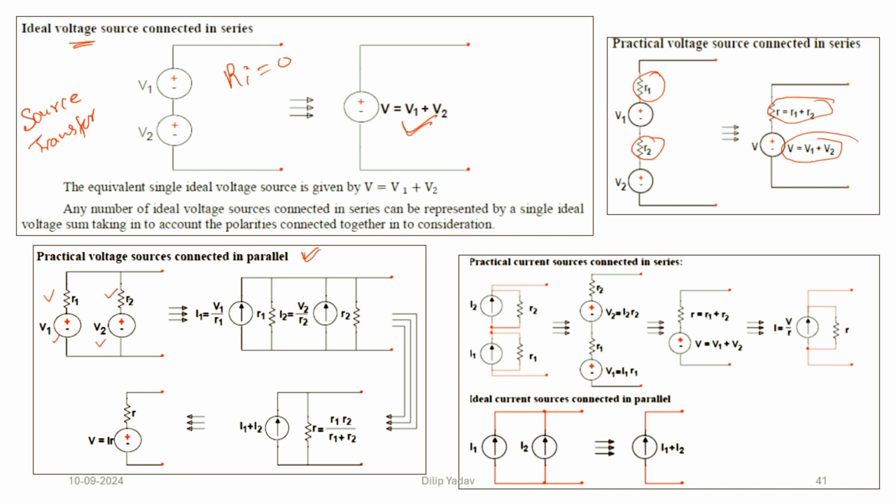So by using this, we have transformed the voltage source into the current source. The current transformation is there, and I1 is calculated like this, and I2 and R2 are calculated like this. This is I1 and this is I2. So we have transformed it. The two are connected in the parallel, so the current will be equal to I1 plus I2, whereas the equivalent resistance of these two connected in the parallel will be like this. So the equivalent can be drawn like this.